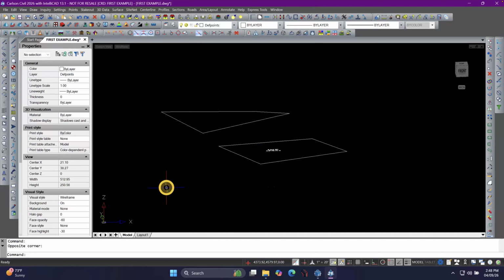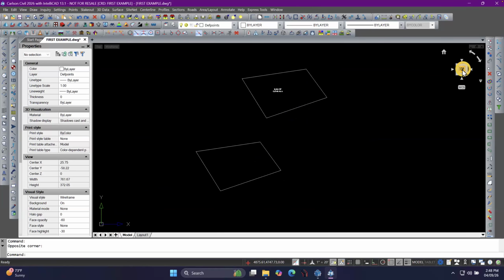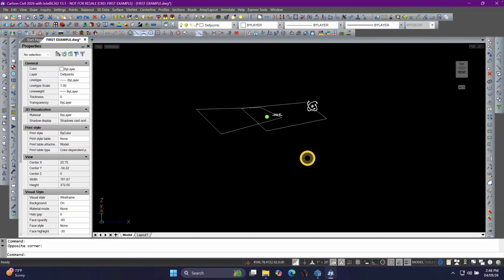Yes, Doris. So, can you repeat again? Yeah. So here I am in my top view. I can use this little cube to change my viewpoint around, or I can hold the shift key on the keyboard and press and hold the wheel on your mouse. You've got a wheel in between the two buttons, right? Yes. So press that and hold it, keep everything held down, and then just push the mouse around.